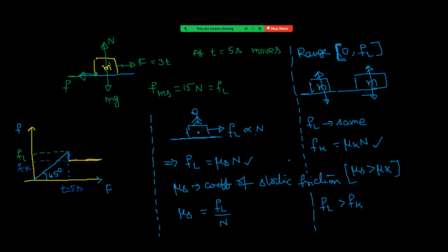Okay, so coming to kinetic friction, there is no confusion. Simply multiply mu k value with normal reaction. But while taking static friction, it can have any value from 0 to the limiting value. So while making calculations for static friction, we should be very careful.